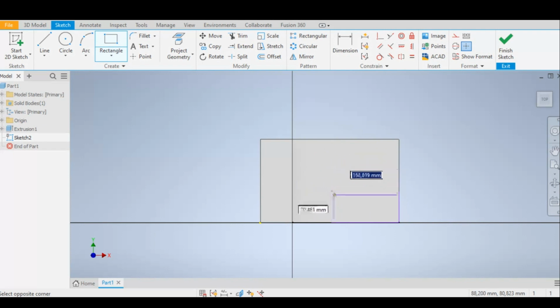So as you can see, I've selected at the corner there, and from this, the rectangle, I can then enter the length and the width of this rectangle. So let's just enter this length of this, and once I click tab on my keyboard, I will then be able to select the width of this as well. So I'm not going to press enter immediately.